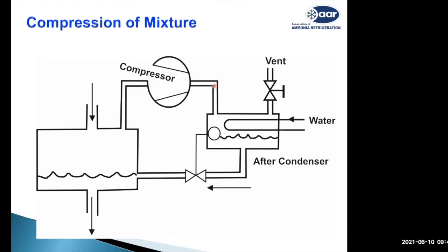It gets compressed and then put into the heat exchanger where you have a subcooled refrigerant, and if the gases coming from this receiver are ammonia, they get condensed because of the low temperature. They are put back into the system. If they are non-condensables, they accumulate on the top side of that heat exchanger, and then those are vented outside.